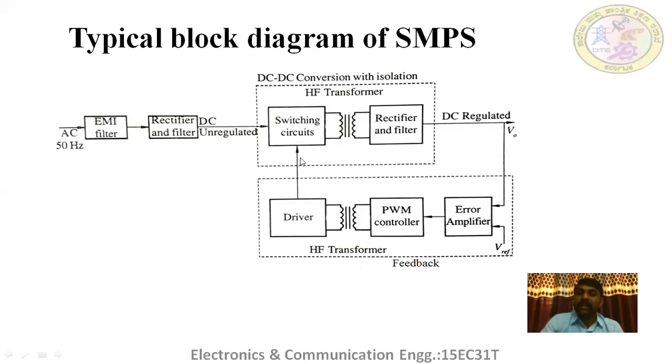This driver drives the switching circuit or the switch of the SMPS. By changing the duration of the clock pulse, that is the duty cycle, we can change the duration of on and off of the pass element. Likewise, the output is maintained at constant.